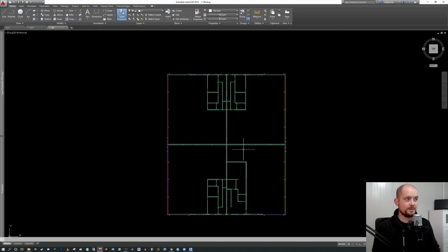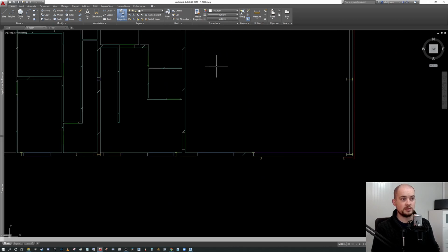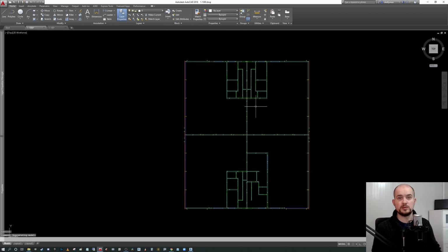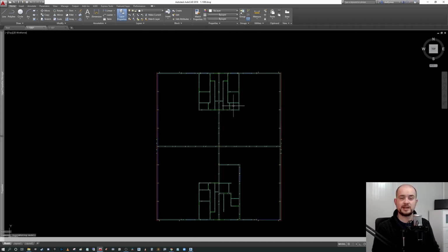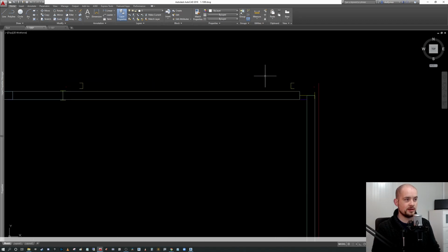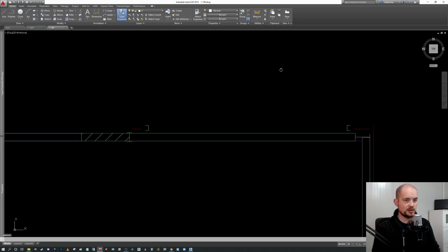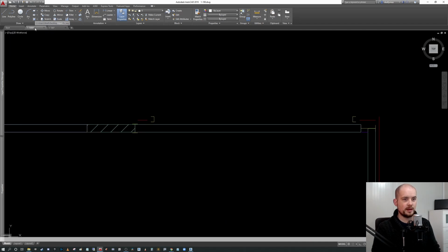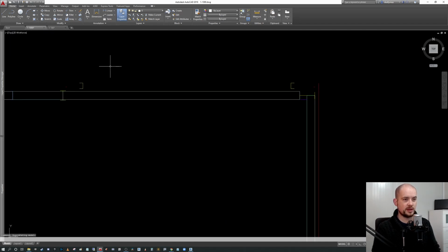Okay, now going to the 1:1000, from a bird's eye view, it looks much the same, with the exception of obviously the hatch patterns aren't as dense. But going to the purlin there, looking at the same location, that's your 1:100 compared to your 1:1000. You can see that there's a problem with the purlin line length.